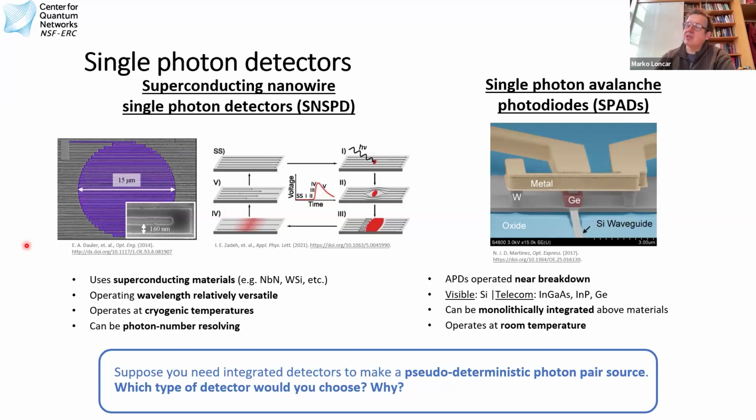They're all related. The spontaneous emission factor tells you which fraction of spontaneous emission goes into the mode of interest, in this case a waveguide mode, as opposed to emitting into free space. It turns out for a simple waveguide that's not very high, so you end up emitting a lot of light into free space, and collection efficiency goes down.